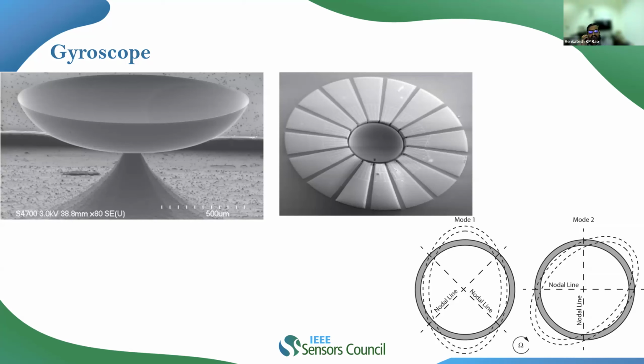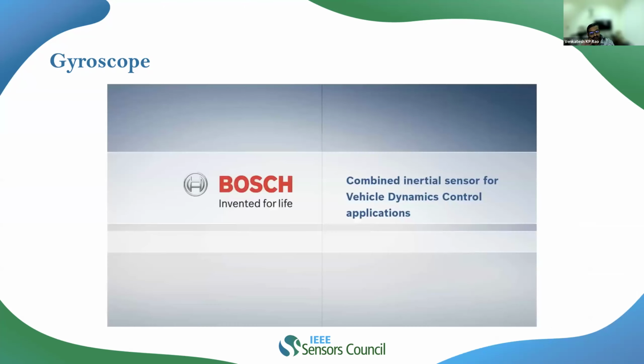So decoupling and frequency tuning play a very, very important role in a gyro. Since it is a spherical structure, we do get the degenerate modes. Since we have the degenerate modes, this will improve the sensitivity tremendously, right? So this is the working principle of the Bosch gyro.